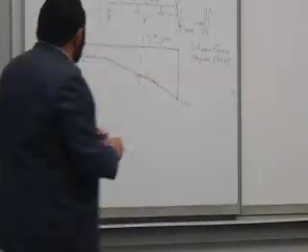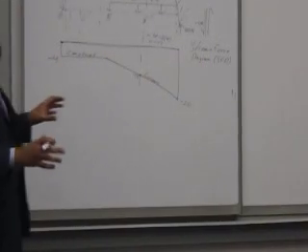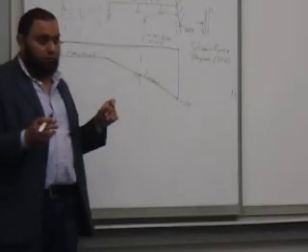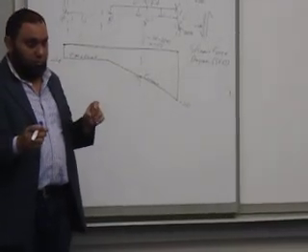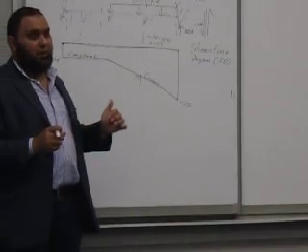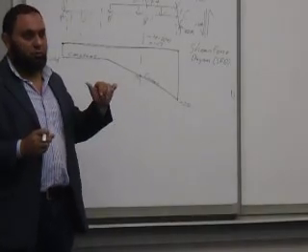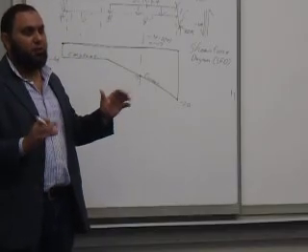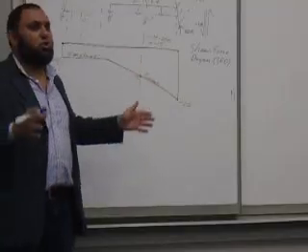So again, pay attention, we reached some kind of a rule in the shear force. Where do I do my cut? I'll do my cut after and before each change in my load and each change in my geometry.